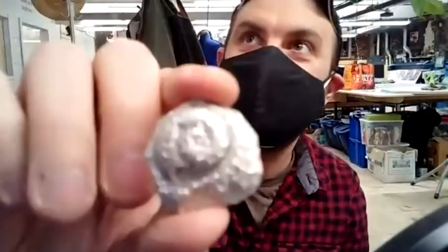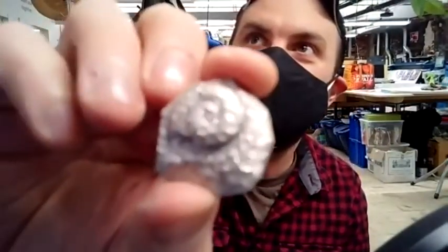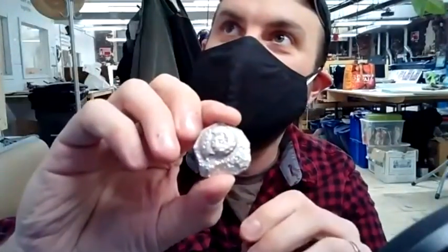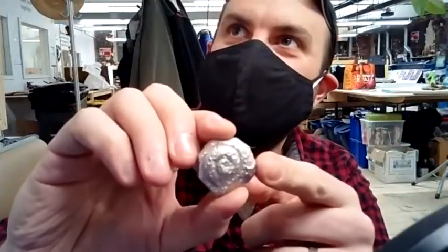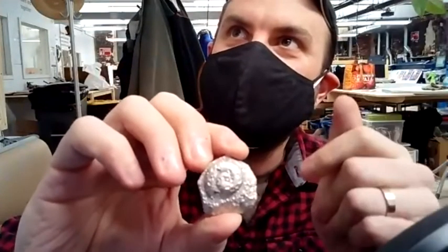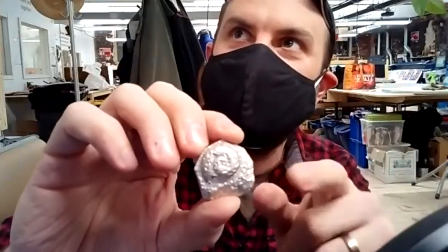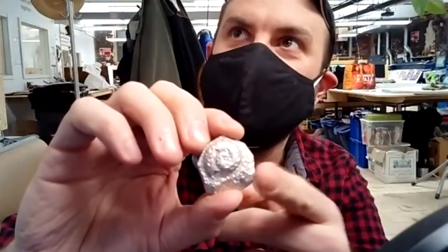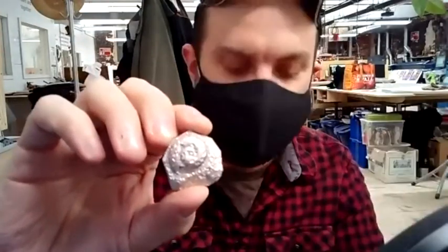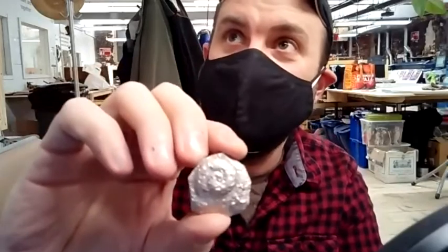From there, I did get a cast, but you can see the surface finish. And hold on, if I can focus this a little bit better. The surface on it is all pitted with holes. And Julia was pretty clear: it's hardening as soon as it hits the silicone. So in order to cast metal like this, I need to preheat my silicone so that it's already hot. And she said I can just microwave it. I haven't been able to try it since she made that recommendation, but it's neat.